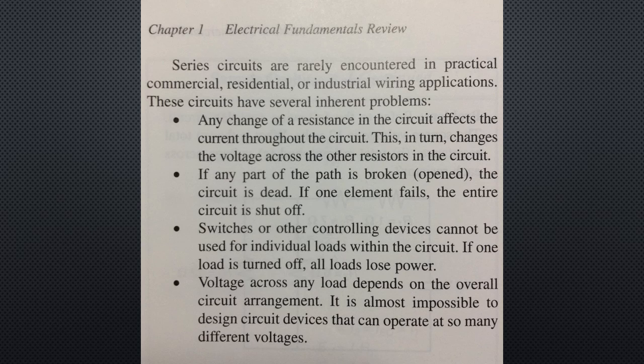Third, switches or other controlling devices cannot be used for individual loads within the circuit. If one load is turned off, all loads lose power. Again, or at least some loads may lose power. Fourth disadvantage is that voltage across any load depends on the overall circuit arrangement. It is almost impossible to design circuit devices that can operate at so many different voltages.